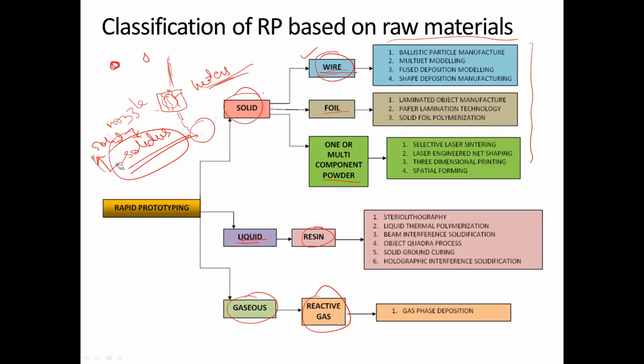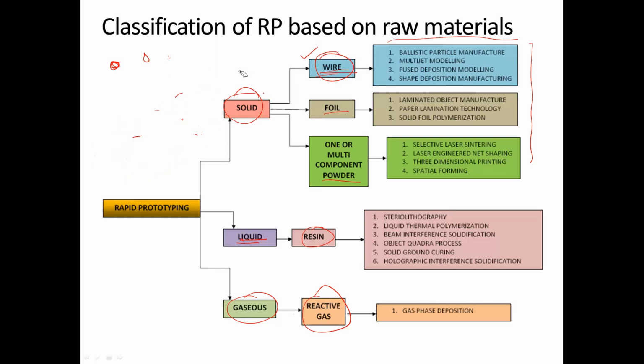Okay. Now let us come to the mechanism of sheets. Now under sheets, what basically happens is, here the action of laser or the mechanism of heat is actually completely different from the other systems. Under foil, what happens is that here is a laser system. This is your laser system. Generally, it is CO2 laser of around 10 to 40 watts. So we have a CO2 laser, and here you have got a bed.